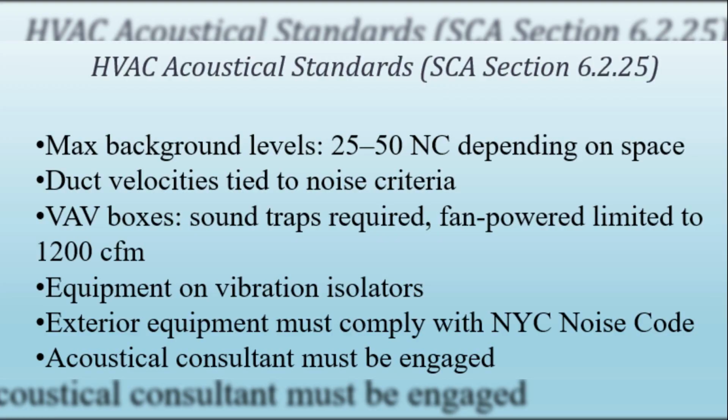Their role includes reviewing the need for sound traps, duct lining thickness, acoustic enclosures, and barriers around noisy equipment. They also determine whether more advanced measures, like floating slabs or special enclosures, are needed for sensitive spaces. To further reduce noise, heat pumps and rooftop equipment may require condenser fans with VFD staging, compressor jackets, insulated roof curbs, and acoustically lined outdoor air intakes. In short, Section 6.2.25 ensures that HVAC systems in NYC schools meet the high standards of acoustic comfort required for learning, by combining design limits, careful installation, noise isolation, and professional oversight.